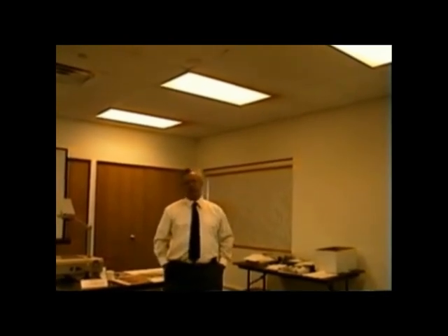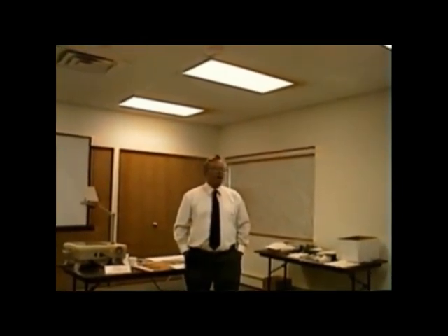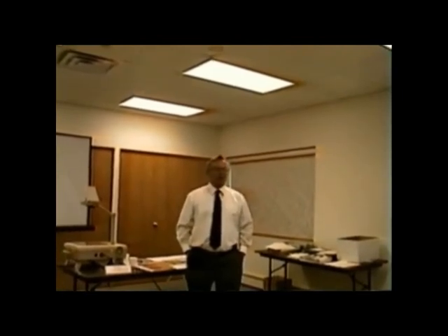Let me back up here a little bit. Venting is a big problem with 90 plus. I can't tell you how many problems we have, and when we talk about it with the contractor, it turns out that we have sags, and we got water, or we got too many elbows. We're making this particular videotape on a day where I got a technical message in my computer this morning from one of our people, asking that the contractor is insisting that he cannot install the furnace unless he uses 10 elbows. Well, you can't use 10 elbows. 6 are maximum. You can't use 10. So he wants to know if he can install it.